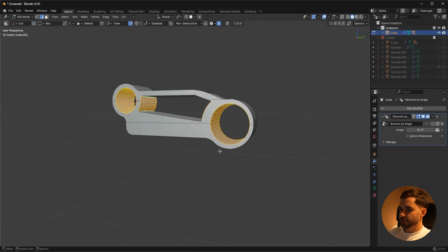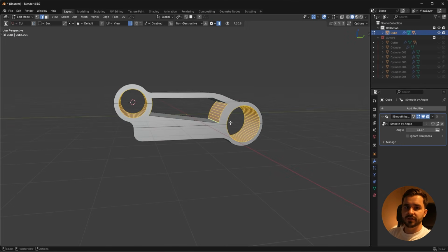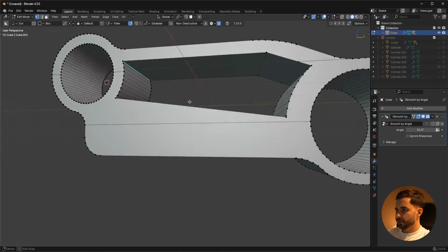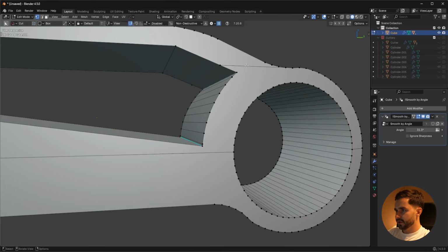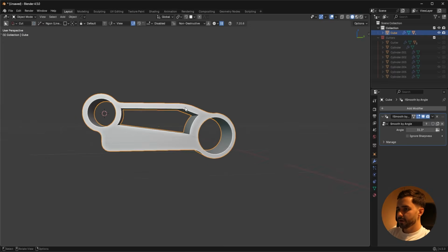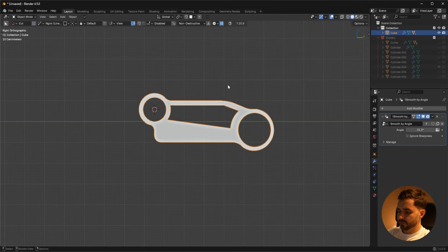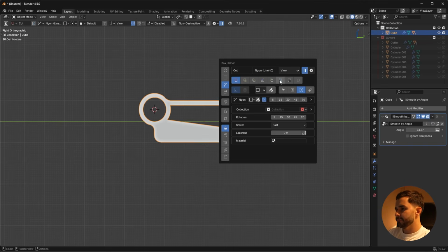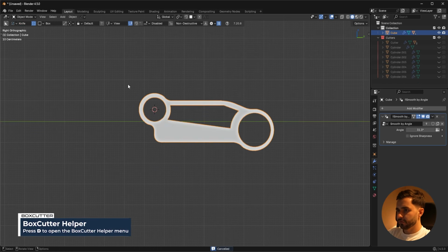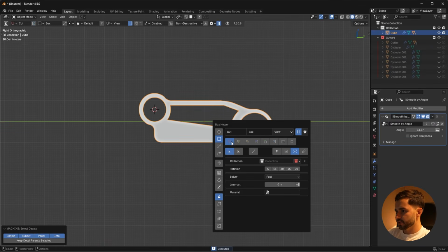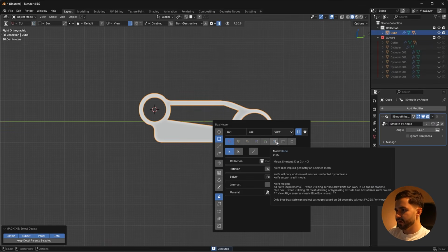So now we're going to have this shape right here, but we're going to have access to the actual geometry, okay? So notice we kind of have these weird connection points. These kind of bother me. If you want to have better connection points, what you can actually do is go to the knife feature and go to box cutter, the actual box, and then just cut straight through. You can change this back to the difference option. I don't really set that to knife by default.